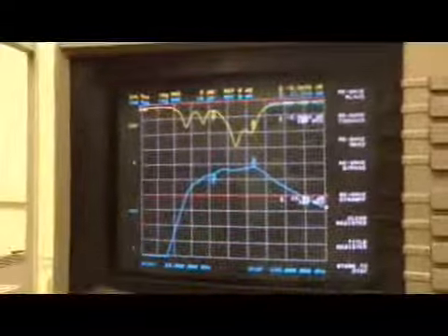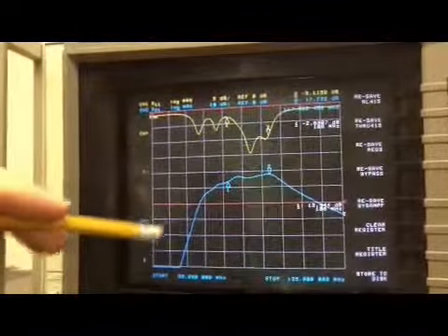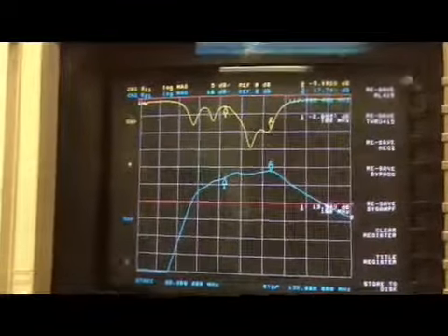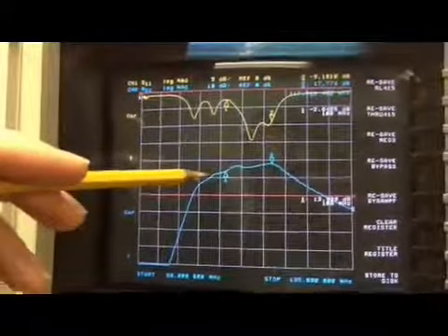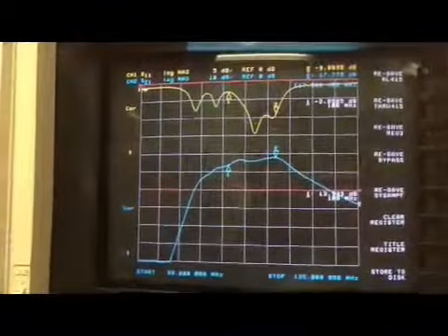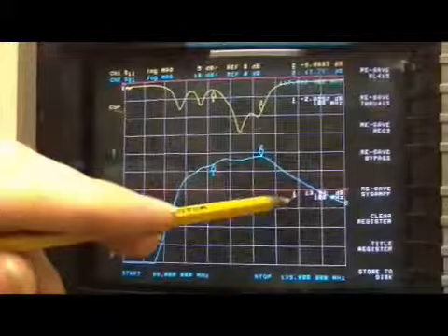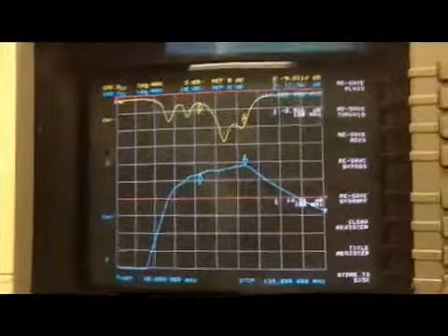Let's see here. Alright, we've zoomed in on our frequencies of interest so we can see how much slope we're looking at on the roll-off in the FM frequencies. As you can see, it rolls off quite quickly. We're still looking at 108 megahertz with point 1 and 118 megahertz with point 2. At 108 megahertz it's still right at 14 dB, so 6 dB of loss.